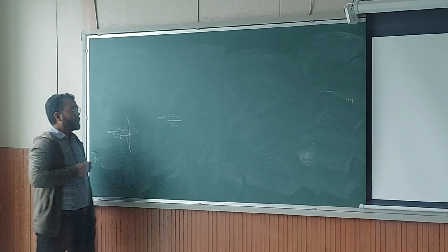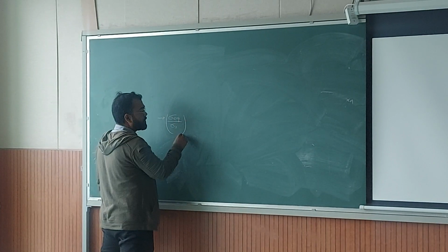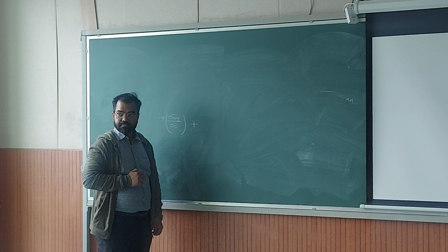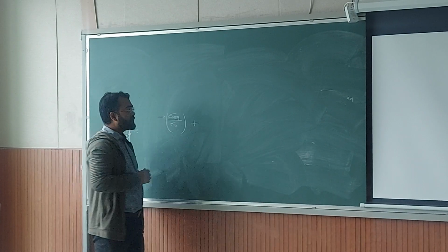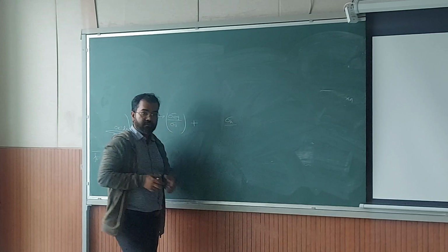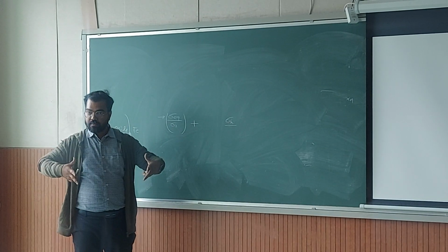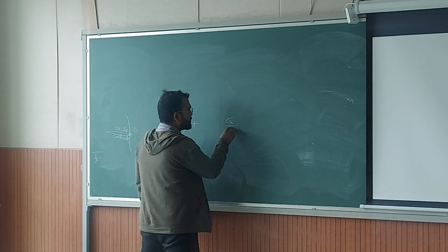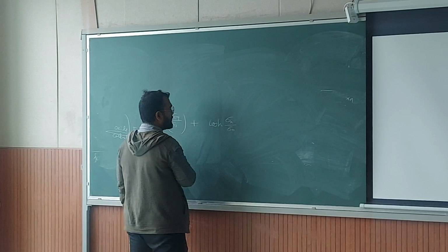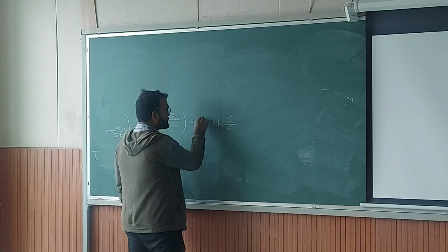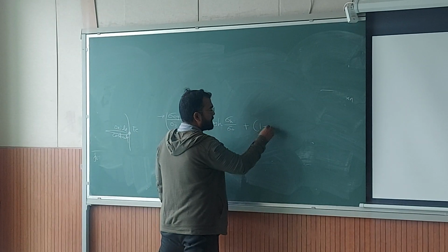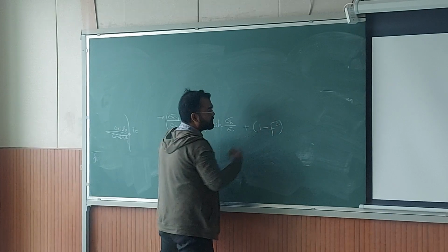Okay, and then you will have growth of these voids, and this void growth is dependent on the hydrostatic stress component because of the volumetric strain. Okay, so then I can normalize that also, and let us say I take a function here, and the amount of void which is forming